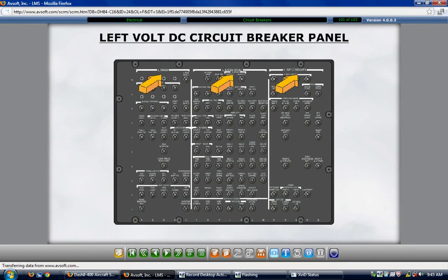The standby, auxiliary, and main battery have the same takeoff maximum load meter limitation of 0.1. The minimum battery temperature for takeoff is -20 degrees Celsius. This concludes the electrical module.